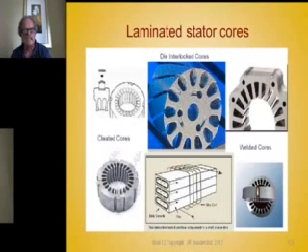They're even able to skew these stacks. In other words, they have servos that will rotate the notching station, or the dimpling station, so that when it puts these together, it gives you a natural skewed stack.